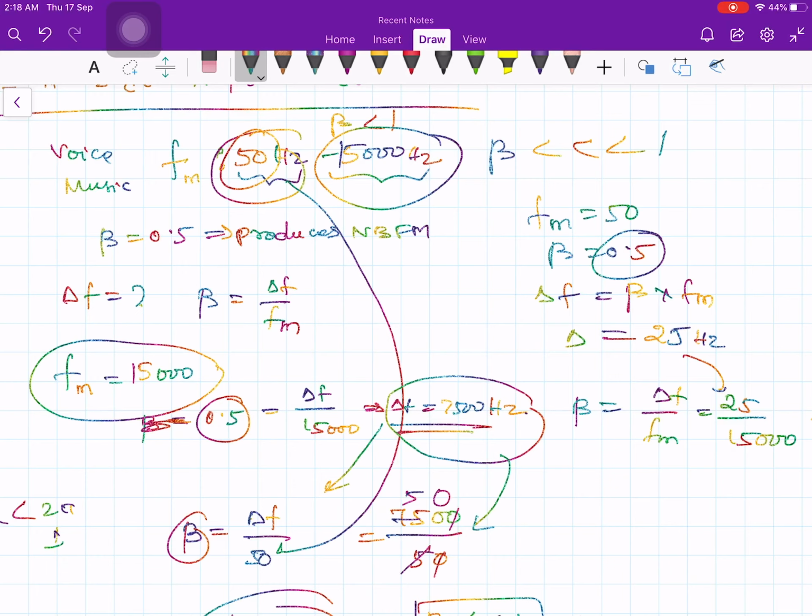Therefore, it can be made highly stable by making use of a crystal oscillator as the starting point, because in the starting point we used a DSB-SC modulator. After that you just multiply the frequency, so you are not doing any further generation of the center frequency. So that is the main advantage of your indirect method. Frequency stability is highly maintained.